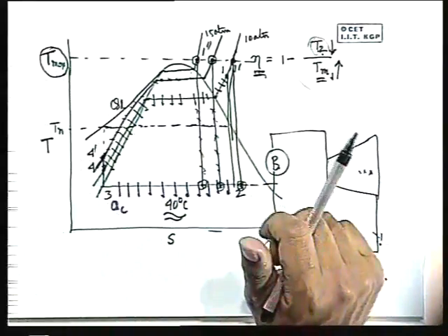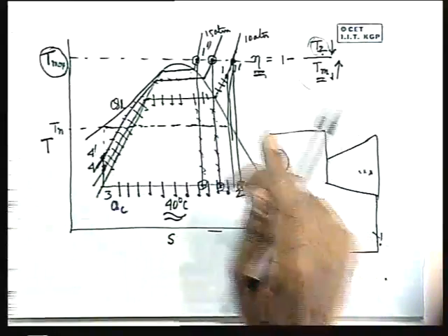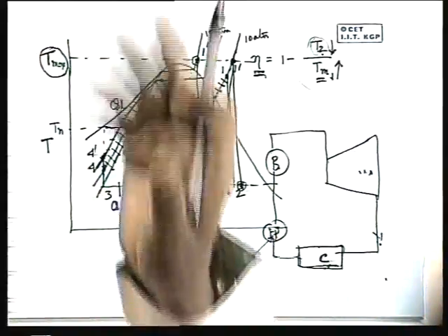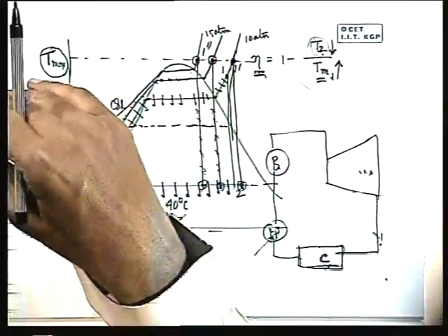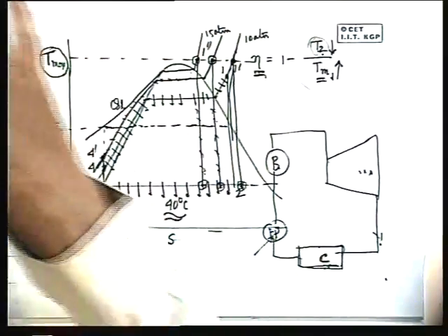Now the question comes up to what level we can go. The very first thing which comes into the mind of an engineer is that probably the minimum level of the pressure will come from the restriction of the vacuum pump. Not the vacuum pump, I am sorry, the restriction of the air infiltration to the condenser. That means if you go on increasing the vacuum, more air will come, and ultimately you will not be able to maintain a vacuum to a very high degree. But it is not so. Even above that a restriction comes.